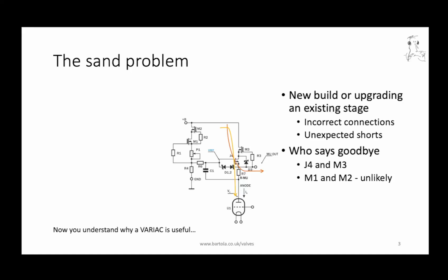So if you are not experienced enough and you cannot solder SMD, and even if you're not very good at desoldering, and we all hate desoldering, and it's not that easy to remove the MOSFETs, for example, in some cases, without damaging the PCB. So if there is a short, and if you're lucky, you don't damage anything else in the amplifier other than the PCB itself and the MOSFETs.